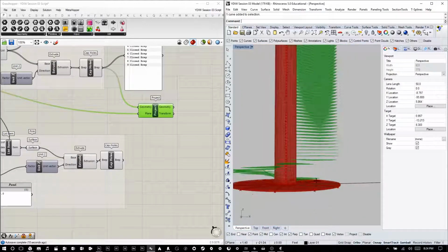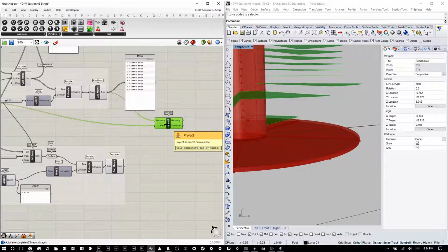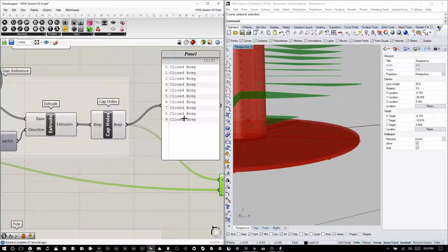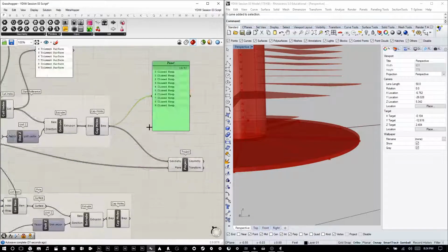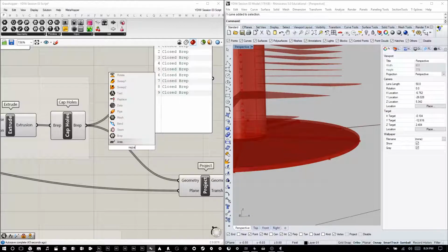So to solve this problem, we're going to use a repeat data component that's going to repeat 0 to 9 86 times in this case. And so now we'll have it go from 0 to 9 and then do 0 to 9 again, and it'll apply the 9th step to the 10th point and continue all the way up. So we need a repeat data component.